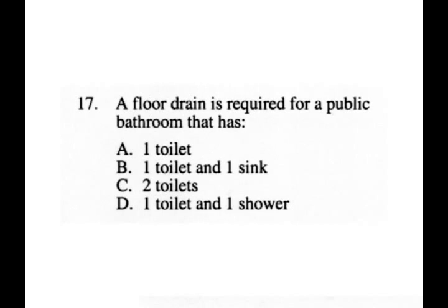Number 17, a floor drain is required for a public bathroom that has... The answer here is letter C, 2 toilets. So if there are 2 toilets or more in a public bathroom, you need to put in a floor drain.